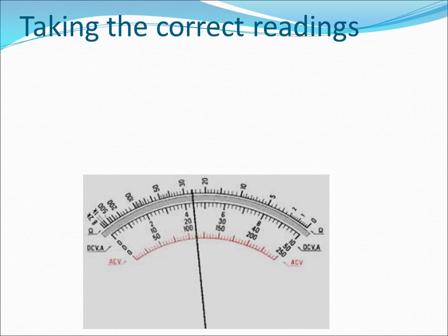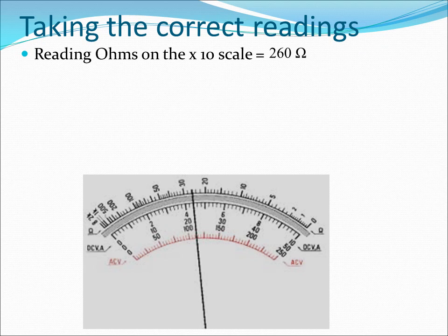Now let us take a reading on the ×10 scale for ohms. Determine the reading for the needle's position. Stop the video now. You have 3 seconds to do that. The reading is 260 ohms. Now apply this same principle to all the other exercises.